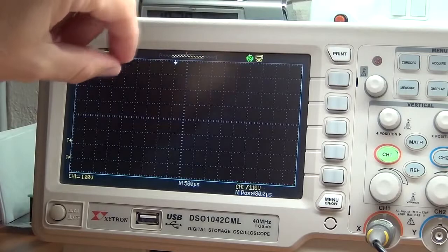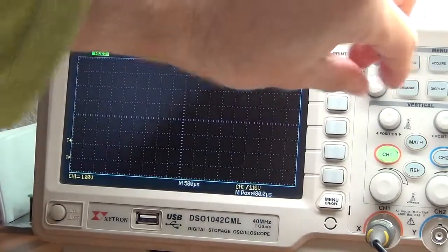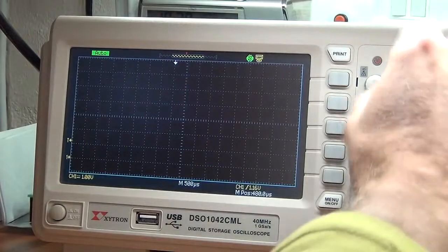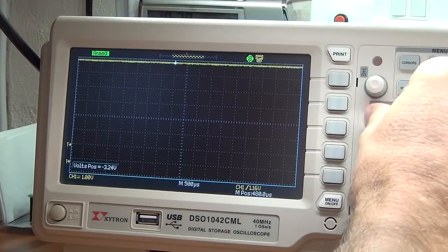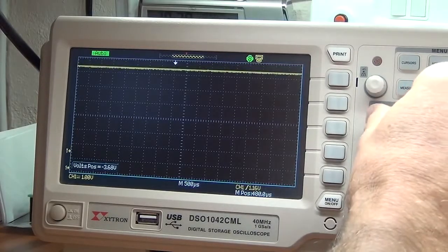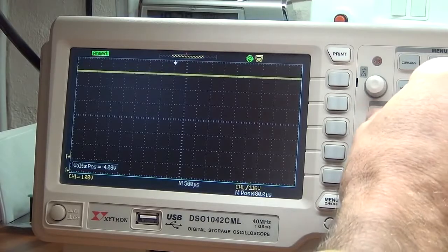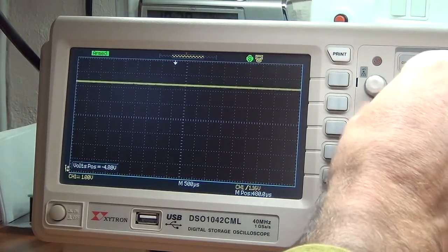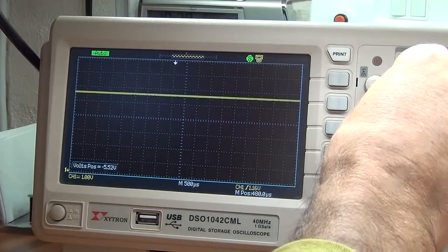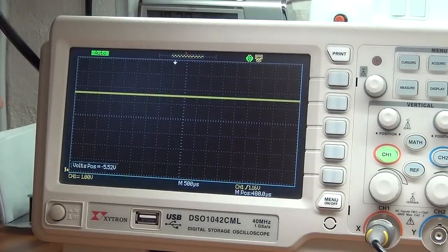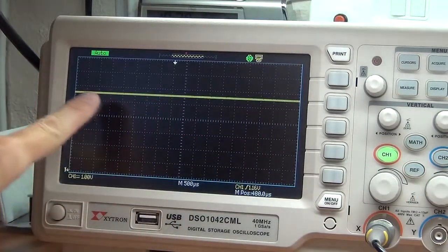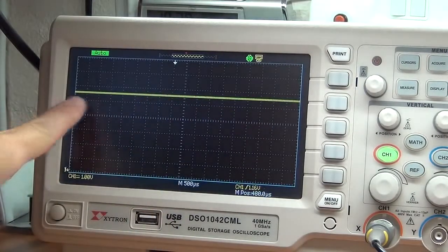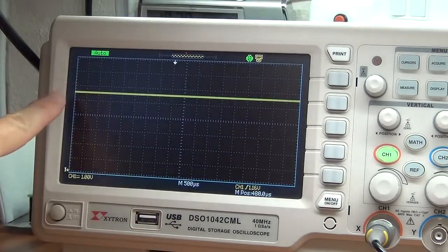So this leads into two things: me showing you what that signal looks like, and then using the buttons or knobs to actually bring signals into view. What I'm doing now, I'm using the vertical position button, which we'll discuss now, to bring that signal down so that we can have a look at it. And as I showed you on that diagram, this is what a multimeter would perfectly represent as a reading if you put it across that battery. It's a straight line because the value is not changing, so it's simply a straight trace across the screen.